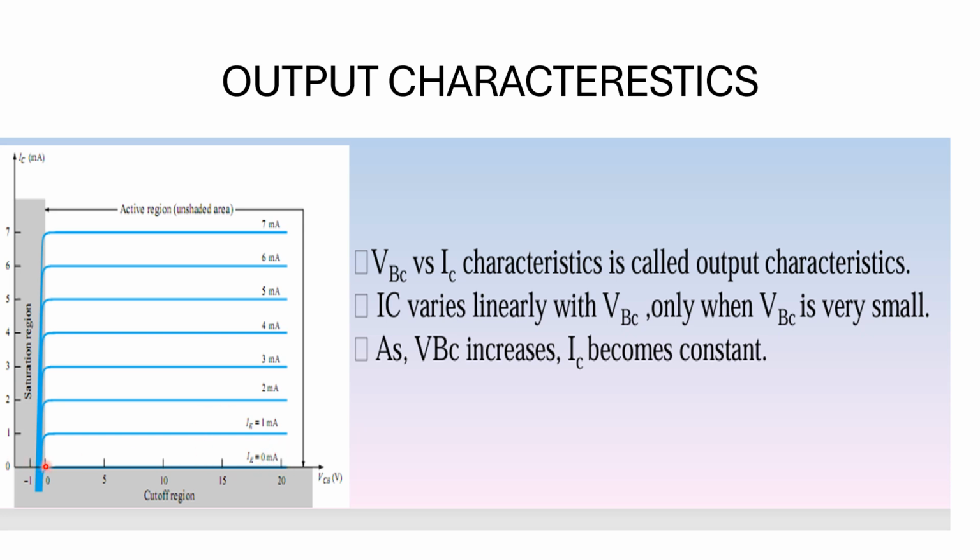Then there is still a small amount of current, called the reverse saturation current, because the collector base junction is reverse biased. Due to that, minority charge carriers move, and the current constituted by minority carriers is called the reverse saturation current, in microamperes.